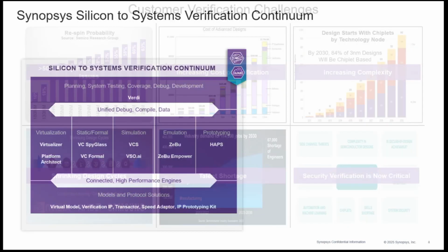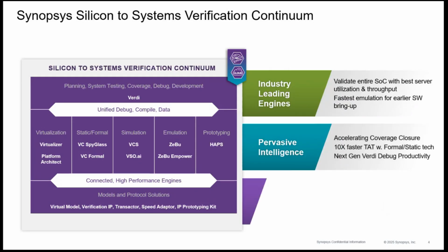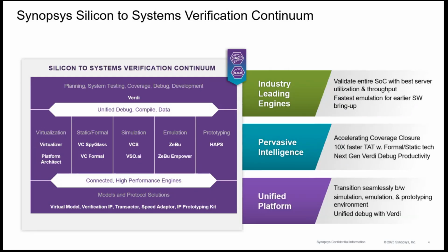Now that said, this is the verification continuum, which is offered by Synopsys. I'll quickly walk you through what you see here. An entire SoC can be verified using the VC simulator, and debugging can be done using the Verdi platform, and static and formal checks can be done with VC Spyglass and VC Formal respectively.